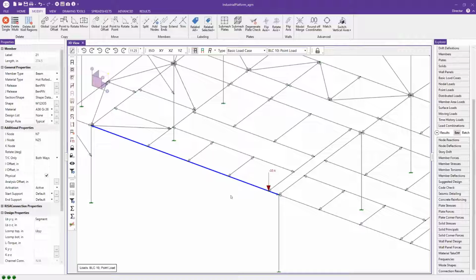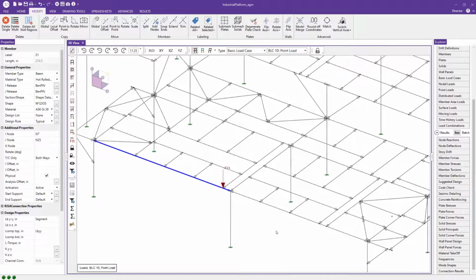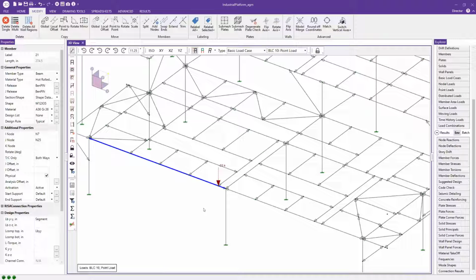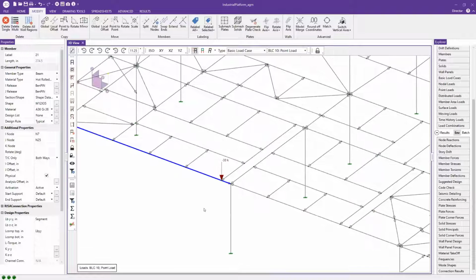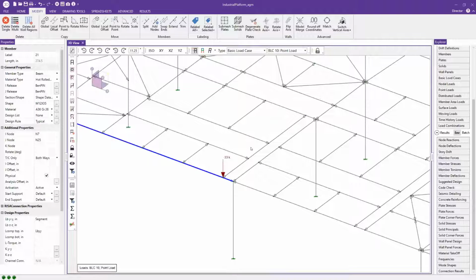So every once in a while, if you get some sort of an odd framing situation like this, that generates a really heavy shear load near the end of a beam, it might be something to watch out for, that doing the usual method might actually under design your connection. So that's just another great way that value is added to the project, both in terms of efficient connections, but also accurate connections and covering all of your bases this way.